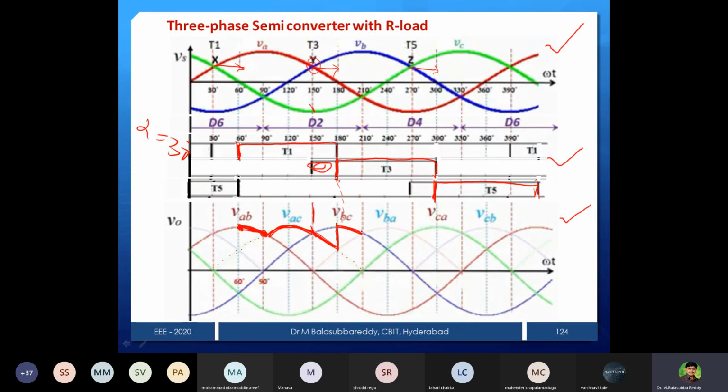And again after this instant, what do we need to see? Lower group. So lower group changeover. What is the changeover? Instead of C phase, now it goes to A phase as it is more negative. That's why your output voltage will be BA. Your output voltage is BA. And then we can see again, still the same, it will continue to conduct. And then coming down, the next C phase device does not have a firing pulse, even though at this point the C phase device is more positive than the B phase device, it will not transfer because at alpha 30 degrees the pulse is, this is the 0 line and this is the 30 line. That's why it will continue to conduct in the previous BA only, then it will shift to CA, like this. Then it goes to CB like this.